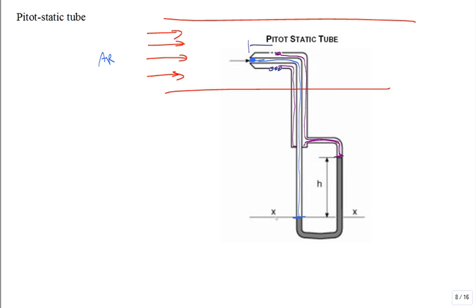So what you're saying is the air right here at the tip of this pitot tube has higher pressure than the air on the sides of the pitot tube. Okay, what you do now is you back up and you apply Bernoulli's equation to little chunks of air. Some of them are starting out right here, and they just flow, and they're going to hit dead on to the tip of that pitot tube.